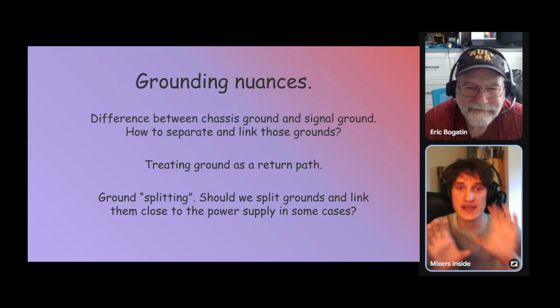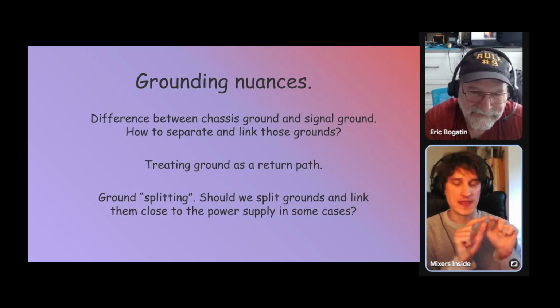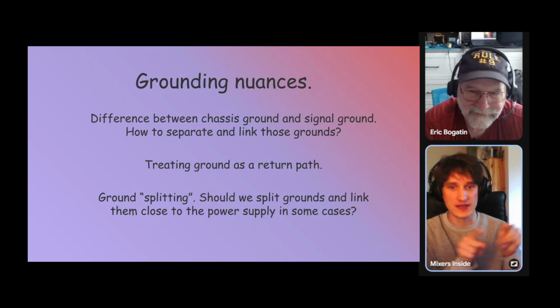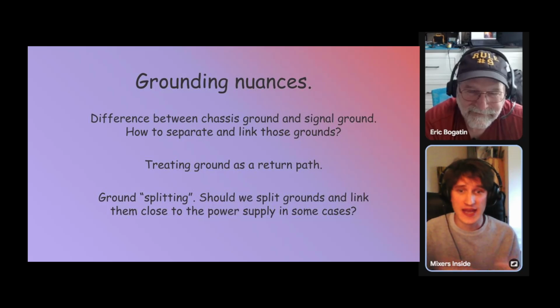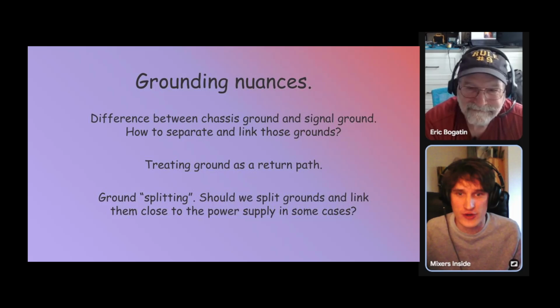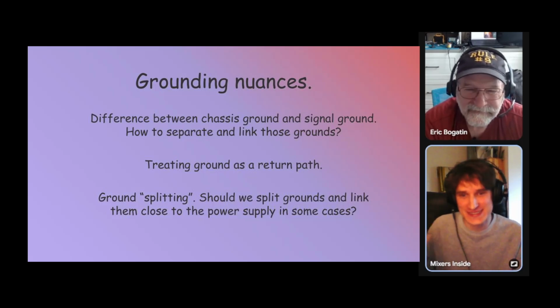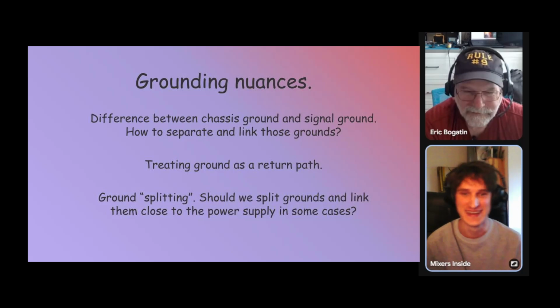And then when I separated it and made a cut, like a power supply zone and a signal zone, I started to notice that the interference is lower. So I somehow broke the rules. I didn't go with a solid ground plane, but it actually helped me. And this is my confusion.